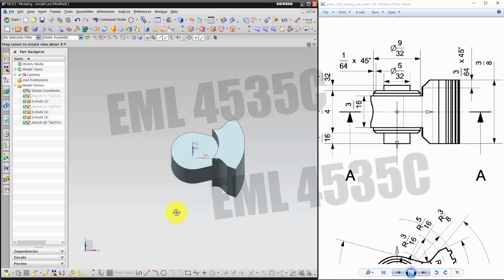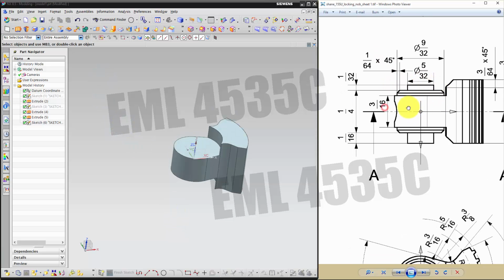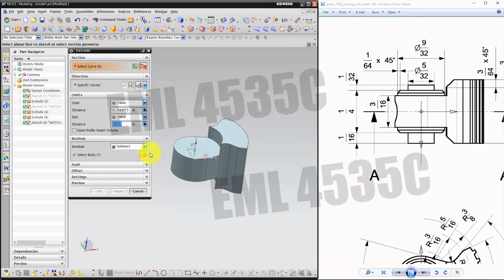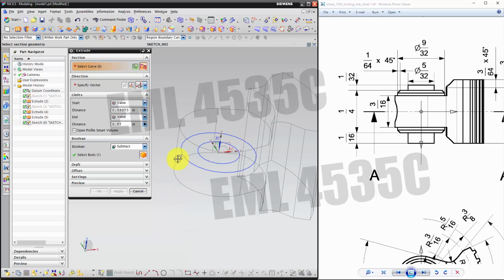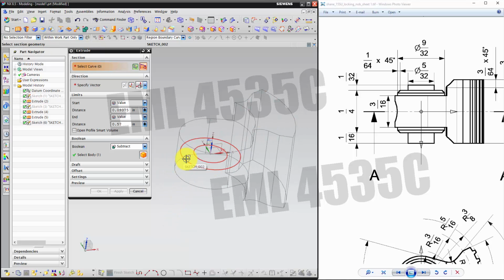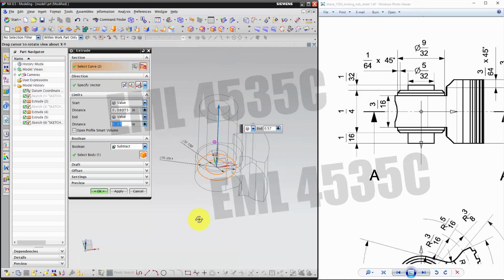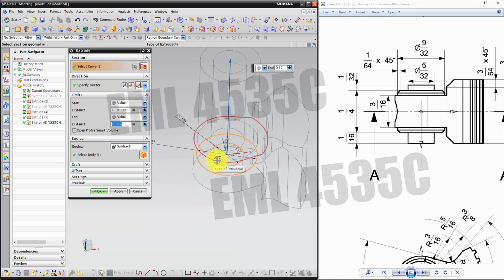Okay, and finish the sketch. The larger cylinder is symmetric. The smaller one is the same as the part we made last week. It's not symmetric. So we'll just start with the smaller one first. I just changed it to a static wireframe so you can see anything inside the solid. You can also hide the extrude. And here, if you select the region boundary curve, it'll just extrude this tube shape.